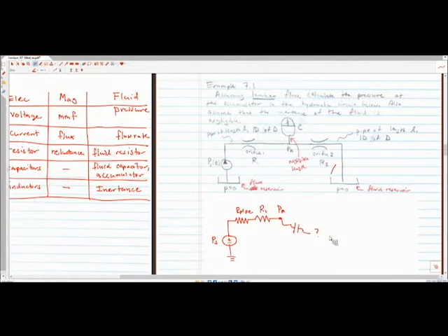So we're going to have this capacitor connected, where at one end it's going to be PA. That's where its inlet is physically connected, to this tap at PA. And then the other end is going to be at ground, because the storage of pressure in the system is going to be referenced to atmospheric pressure. Okay. Any questions or ideas? This one trips up students quite often.